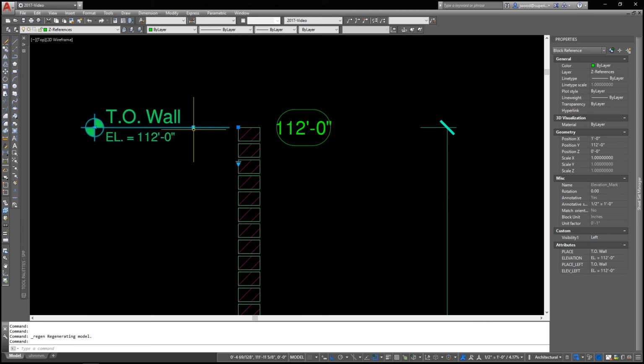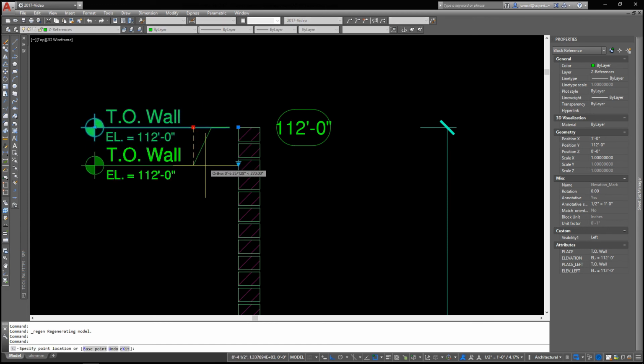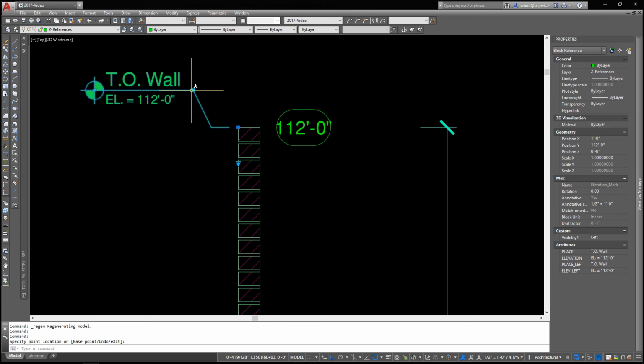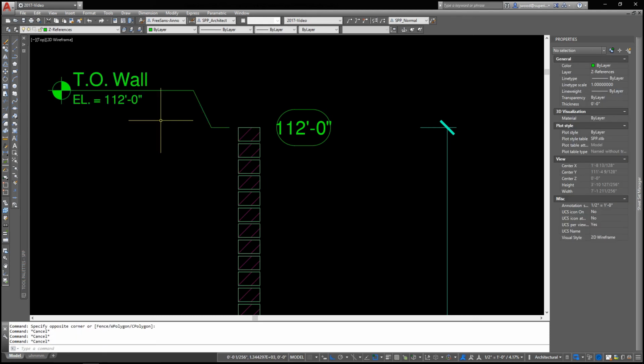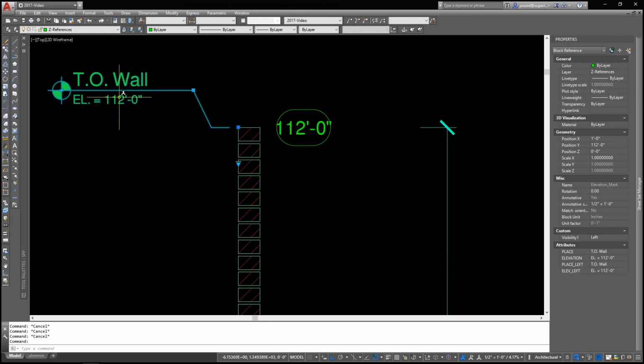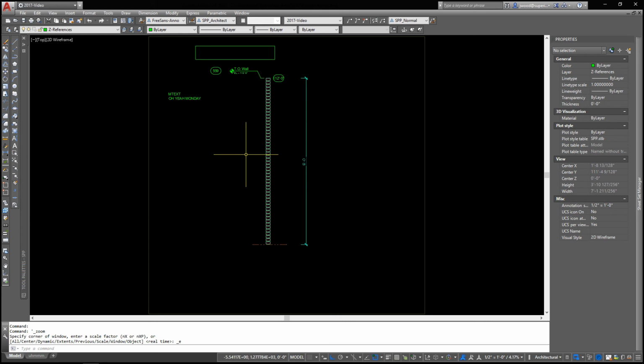But as you can see, when you add in all of the various dynamic block things that you can do, such as stretch points and arbitrary points and all that stuff, and your left and right mirroring using lookup tables and all that stuff, and you add in some intelligence as to where that block has been inserted at using fields, you can make yourself a nifty little combination. So there you have it. That is a brief overview of some of the stuff you can do using fields, especially when you combine them with other dynamic block properties.